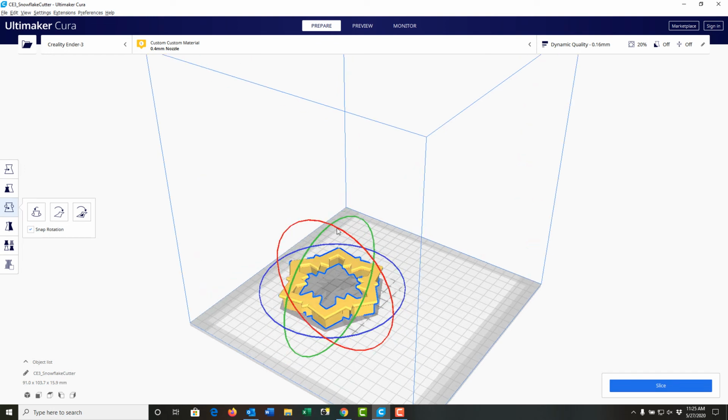So these rotation rings allow me to rotate it, but I want this face to be down. That's how it was designed, to be self-supporting and print without any support. And hence part of the challenge for this lab isn't just designing a part for self-supporting, but setting it up so the software doesn't add support. The Cura software is great. It knows my machine does not have support material, but it'll go ahead and it'll add breakaway support where needed if you tell it to.